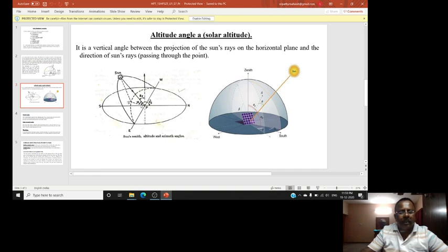These are the horizontal lines which are going here, solar horizontal lines, and from here to here, this plane is nothing but the solar azimuth angle. It is the angle between the horizontal projection of the sun rays and the due south line, going in the clockwise direction.